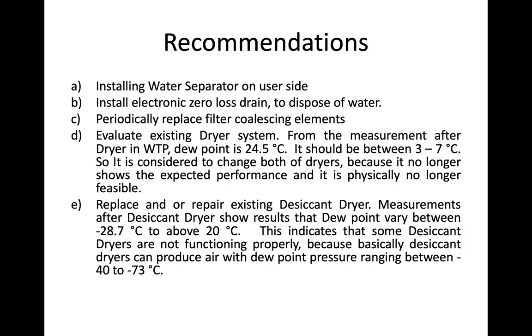So from this measurement, we have some recommendations. The first recommendation is we suggest installing water separators on the user side, to remove the potential of problems in the future due to the water content in the compressed air. The second recommendation is to install an electronic zero loss drain to dispose of wet water. The third one is to periodically replace filter coalescing elements.